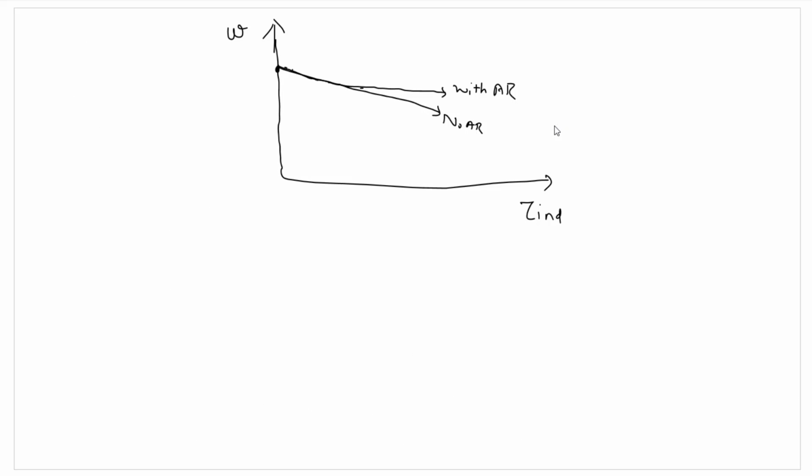So for lower decreases of phi, phi and phi square will be almost similar, and there will not be much effect, but for higher decreases, there will be a dominating effect of phi square over phi. So eventually the speed will increase with the armature reaction.